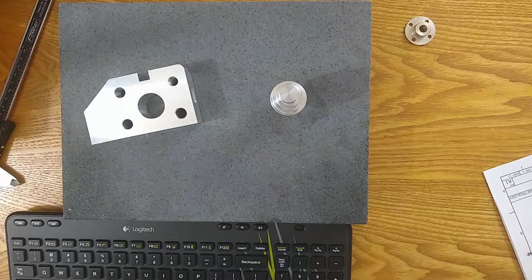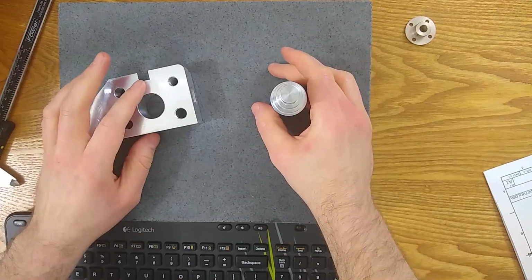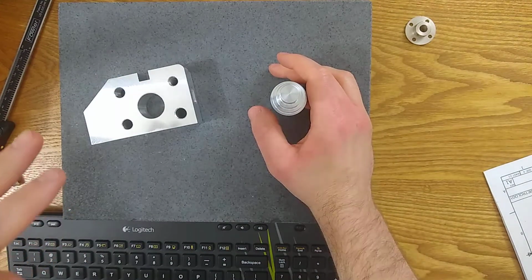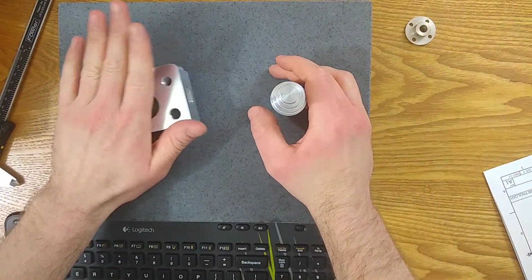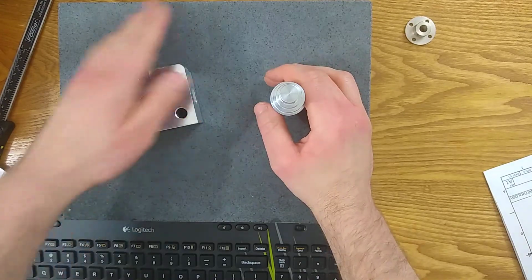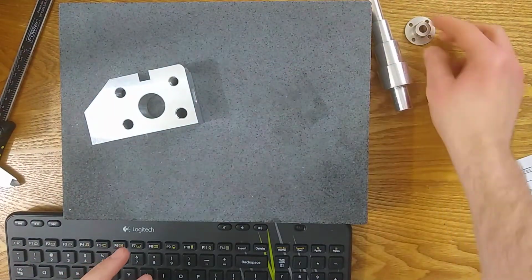And so we control it with a circularity or a cylindricity callout. That restriction feeds back into the manufacturing method so that it can pass, and it feeds into the inspection method so you can verify it. So feature control frames are really important.